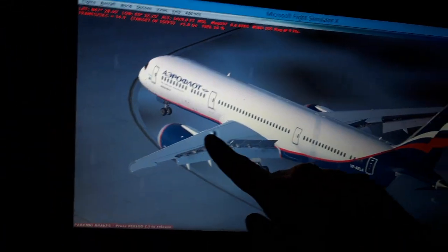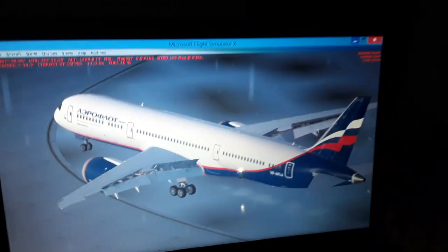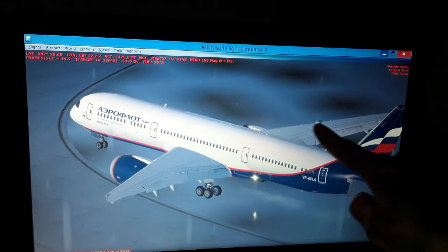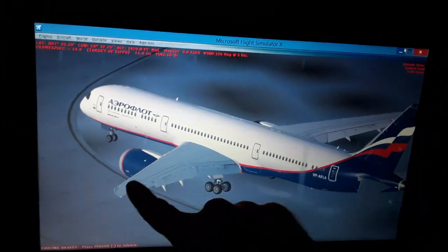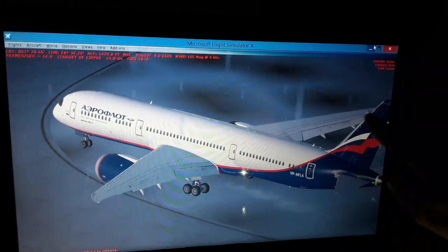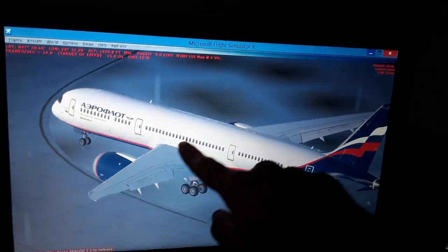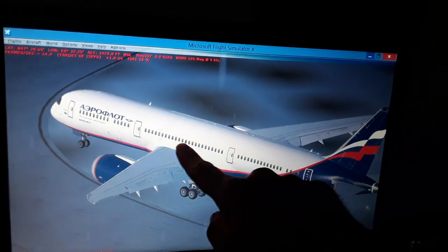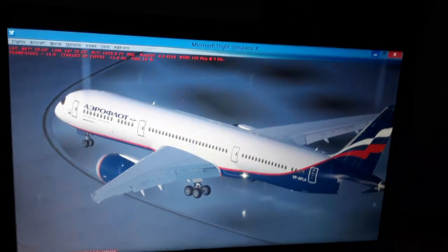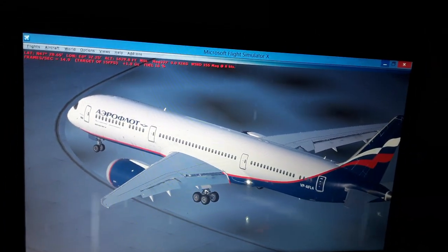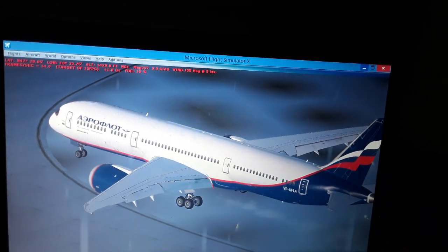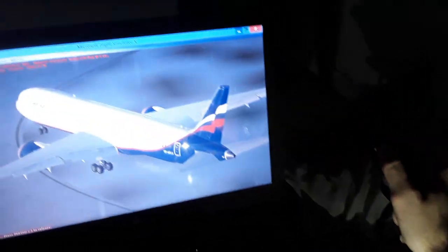That is also where the mean aerodynamic chord of the forward wings is, located at 23% MAC for this flight, where the maximum aerodynamic lift occurs in the forward wings on the top surface as we fly, and also the center of gravity through here, and the fuel on board in the left and right wing tanks and the center tank. It is also where the stall will begin, when the top surface airflow of the wings becomes detached, and there we have the stall. So we need to avoid the stall. I will talk to you about that later.